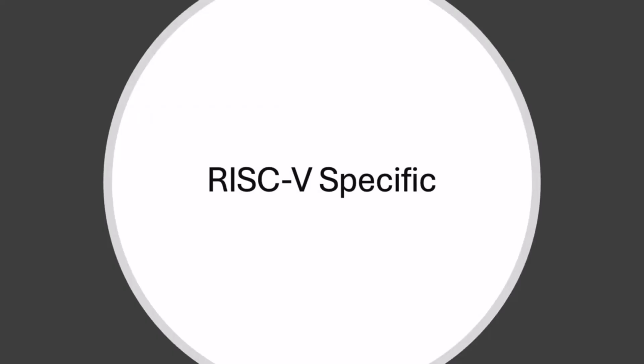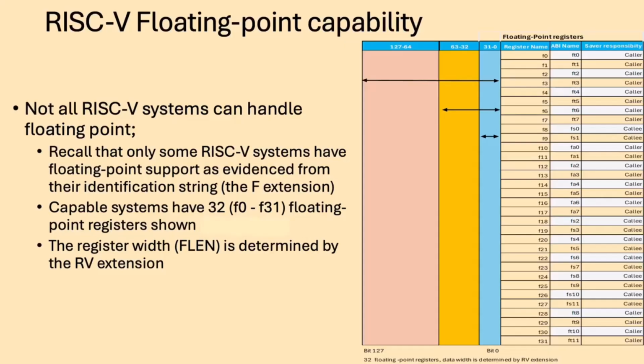Alright. Heavy going. But we've now reached the second part of the tutorial, so stick with it. Now that we've got a basic grounding, it's time to look at how RISC-V can handle floating-point instructions. So first of all, let's look at the floating-point registers. They are similar to the integer X registers that we know about. There's 32 floating-point registers. They also have ABI alias names, which should be adhered to along with caller/callee responsibilities. We use the term FLEN instead of XLEN for the register width.